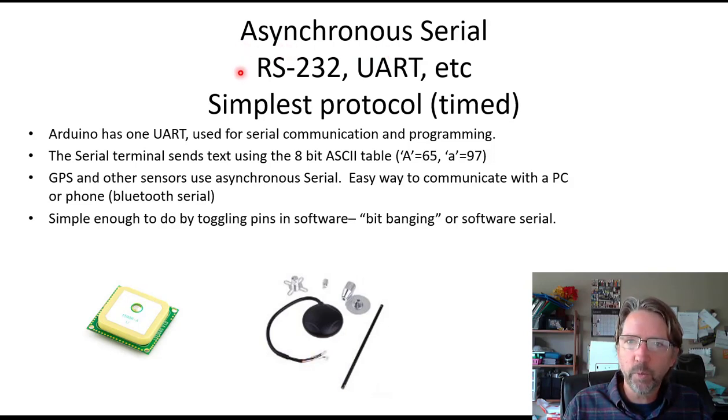It's also what an RS-232 serial port uses, which are in old computers that have serial ports like this. UART is another abbreviation for that. Universal Asynchronous Receiver Transmitter is what UART stands for. So sometimes just serial port, sometimes they call it a UART. RS-232 and RS-485 are using asynchronous serial with specific voltages. So a lot of names. This has been around a long time.